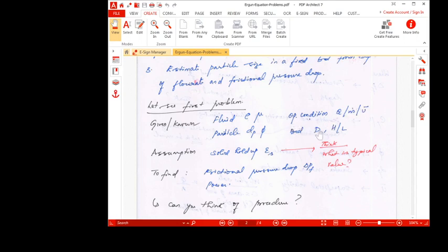The bed dimension is the diameter of the bed or the height or the length of the bed. And the particle properties are known. What I mean by particle properties here is the particle size and the sphericity. Typically, hold up or the void fraction should be given as part of the question, but if it is not there, we can safely assume this. Can you think of what is the typical value of this solid hold up?